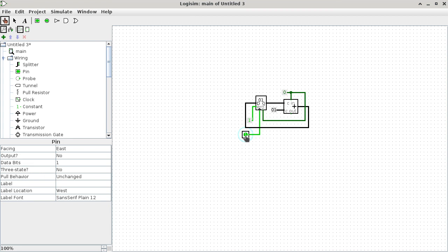So in order for me to go from 0, 1 to 0, 2, I need another rising edge, another rising edge, another rising edge. In other words, I have just made a counter. That's all I have made. It's a counter. Every time the clock is going from 0 to 1, it says, okay, this is kind of the guy at the entrance of Costco.